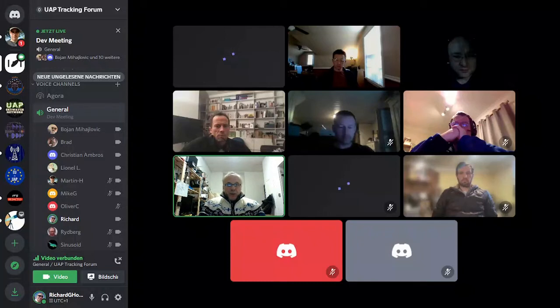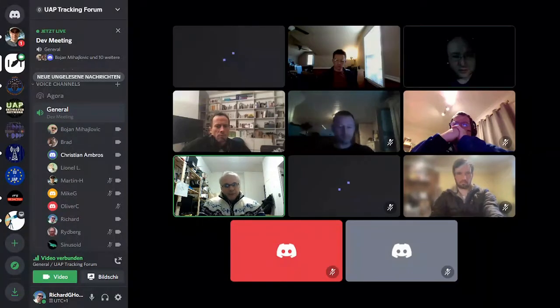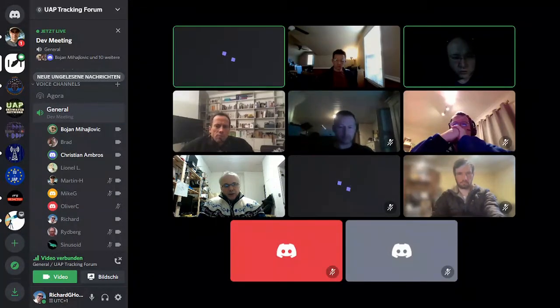So performance-wise, we have to say that when we design our all-sky cam, the camera itself, the fisheye, we have to at least go to 12 megapixels. Otherwise, there's a mismatch between the optical resolution of the fisheye lens itself and the resolution of the sensor. Yeah. It has to match. Due to the Nyquist criteria, it tells us what resolution of the combination between camera and optics we have to choose to get at least our benchmark ISS recorded on 1 pixel.